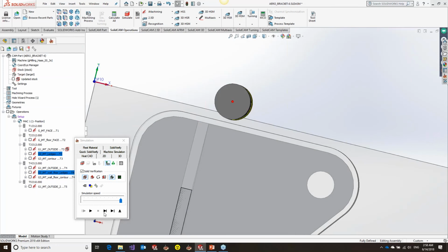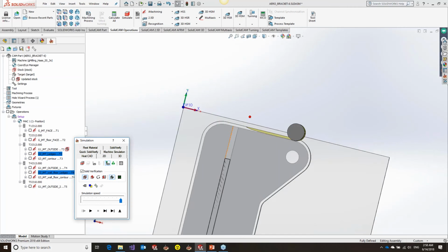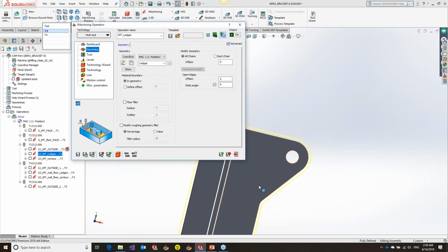Now the tool plunges out in there because it knows there's extra material, and then the cutting can proceed as normal. I can say for anybody who programs in iMachining and uses it for cutting semi-open pockets and things like that, this is a fantastic option. I mean, this is something we've wanted to have for a long time.